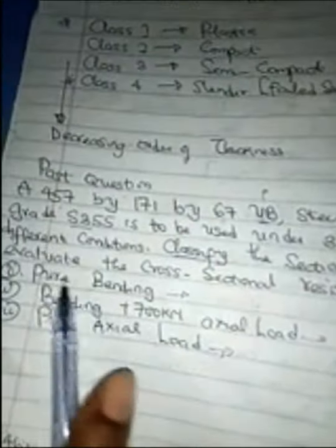Remember, in our question, the first thing they asked us to look for was pure bending. Pure bending occurs when your neutral axis is at your mid depth, at the center. That means this first condition is what we are looking for. This neutral axis at mid depth is used for pure bending. Are we good? So we use the d over t ratio because it tells us that it's the web. Remember, for web we use d over t. We've called it y. Good. So you go to your table.